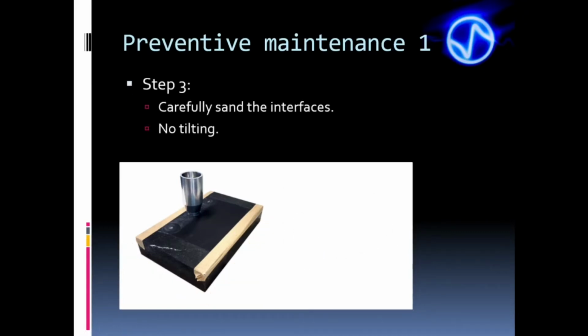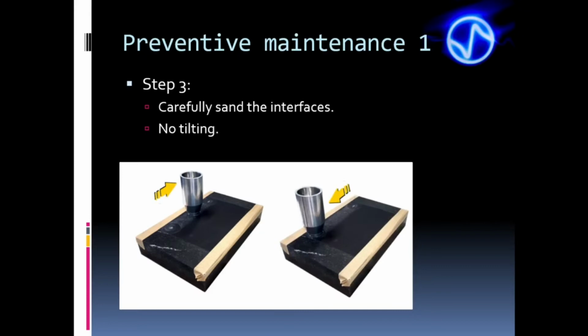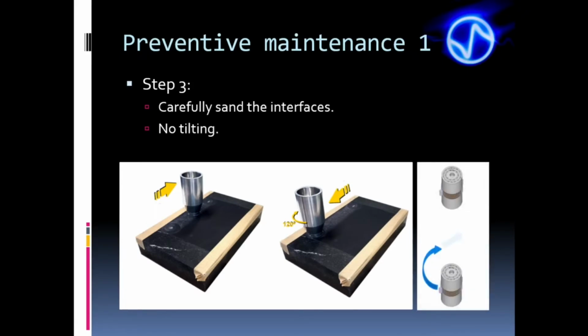For sanding, we recommend stroking the element twice in the same direction and afterwards rotating it a third of a turn. Then, repeating these movements until the element interface is restored. Another way that can be done is the H-shape move. It is essential to prevent the part from tilting during movements, as the interfaces must be parallel as well as smooth. The weight of the part itself must be enough to apply the necessary pressure during the process. If we tilt the part during sanding, we may round the corners of the part, which would be even worse